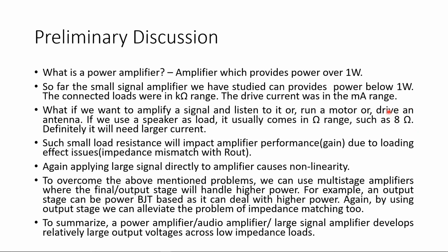This low resistance load, when connected to the output of the amplifier, will definitely degrade the performance of the amplifier due to the loading effect. That is the impedance mismatch with the output resistance of the amplifier. So that's why we require a large signal amplifier.